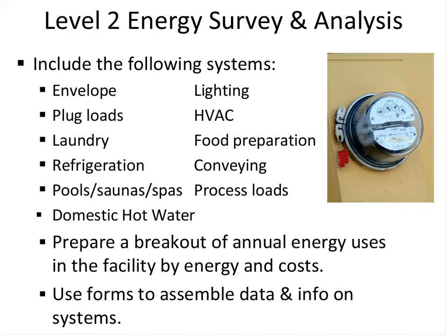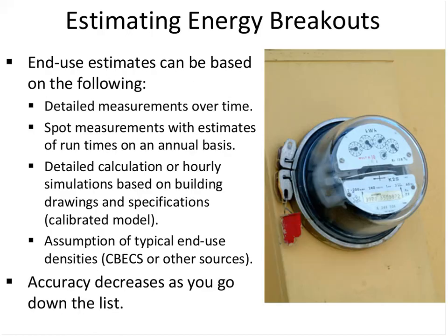Then you can prepare a breakout of the annual energy uses. Estimate the equipment that's in the building, how much it would be using in a typical year, to give a feel for where the energy is going in the building. And there are forms available to assemble this data. So, estimating the energy breakouts.